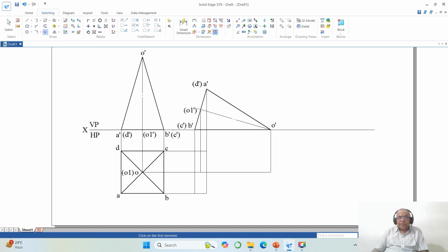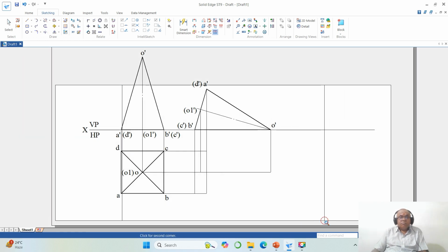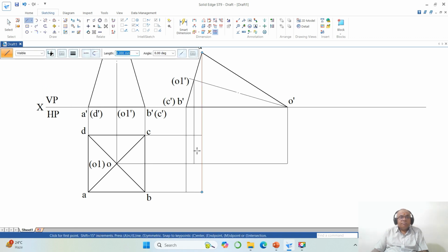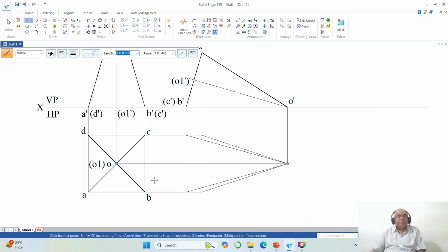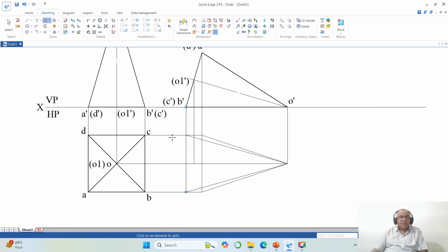now you come down to zoom window. Now you go to line, take endpoint, endpoint, endpoint. Similarly, you take a endpoint to this endpoint to this intersection point. Okay, now you go to split this line till here, then you split this line till here, then you split this line till here, then you split this line till here. Similarly, split within these two.